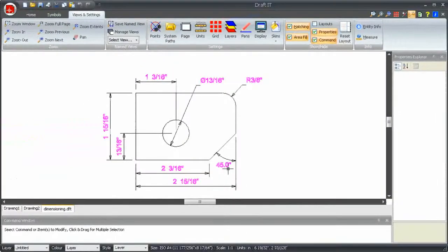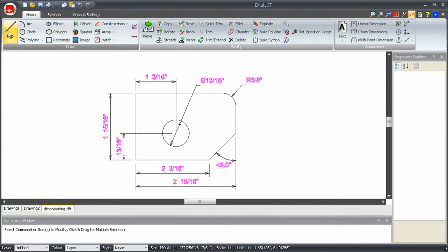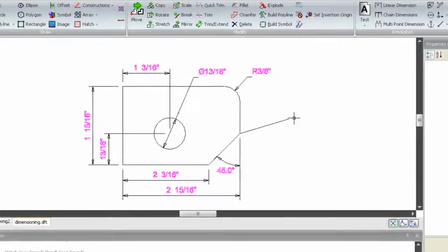When you change units, you will notice a few obvious changes. Firstly, any dimensions on the drawing are automatically converted, and the equivalent rounding accuracy has been set in the new units. Secondly, the status bar reflects the change. And third, any dynamic dimensions, such as when you are in XY mode, also show the new units.